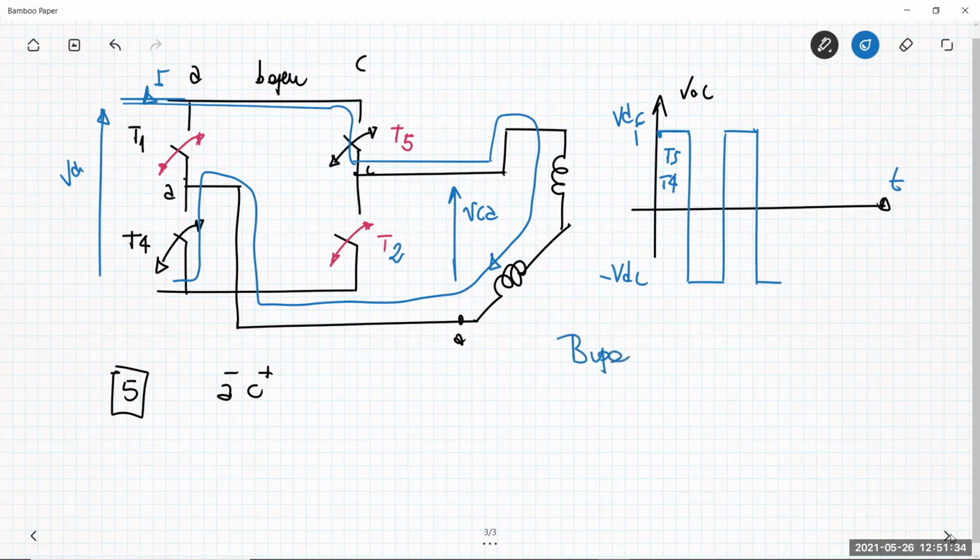This is the bipolar pulse width modulation technique. Basically, you have to take the average quantity, so the filter is represented by the motor itself, and the effective averaged voltage is related to the duty cycle of the commutation, like in standard pulse width modulation inverters. What are the advantages of this pulse width modulation?